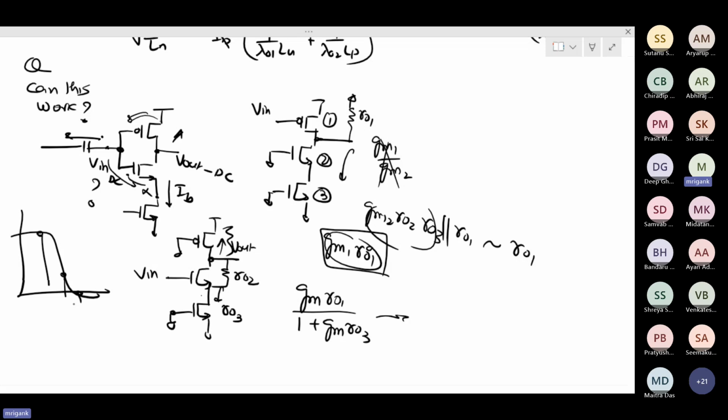If it is not capacitive coupling, another option is to couple directly with the DC. Then maybe you are fixing the DC, but the output is still independent of the input. A small variation in the MOSFET parameters can shift the curve this way or that way, and as a result, you will end up again in unwanted regions. So again, this is not a practical solution. You're not getting any benefit from it. Is that clear?